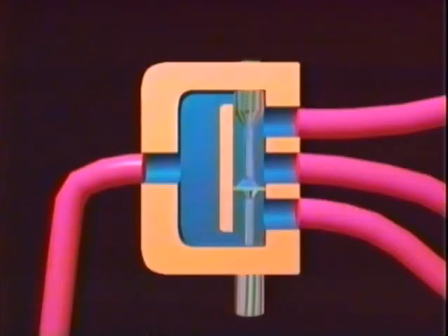The fluid in the upper chamber is forced out and travels through the control valve back to the reservoir. To retract the piston rod, the process is reversed. The valve spool is moved to the lower position, diverting fluid into the cylinder's upper chamber and forcing the piston down.